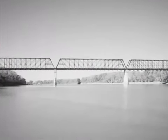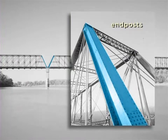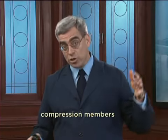We normally think of columns as being oriented vertically, but in practice, any structural member that carries load primarily in compression exhibits essentially that same behavior, independent of its orientation. So, for example, in the Chuto Bridge, these diagonal members, which are called end posts, carry load in compression, and therefore they need to be analyzed as columns, even though they happen to be oriented in a diagonal direction. To avoid confusion, engineers sometimes refer to columns more generally or generically as compression members.